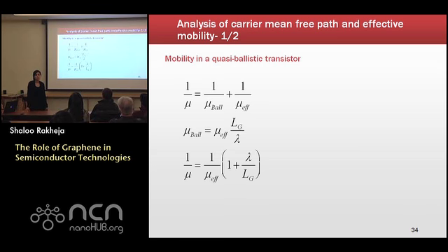In the charge partitioning scheme, you said that you have used the bond pattern partitioning scheme, which is valid in the quasi-static regime. But when you're using an RF circuit in the gigahertz range, do you think that the device is still in the quasi-static regime? Well, for now, I don't know of any other good way to do this charge partition. People have talked about a lot of different kinds of charge partitioning schemes, and this is one of the charge partitioning schemes that I'm presenting. And maybe you can point me to other kinds of charge partitioning schemes that exist in literature.